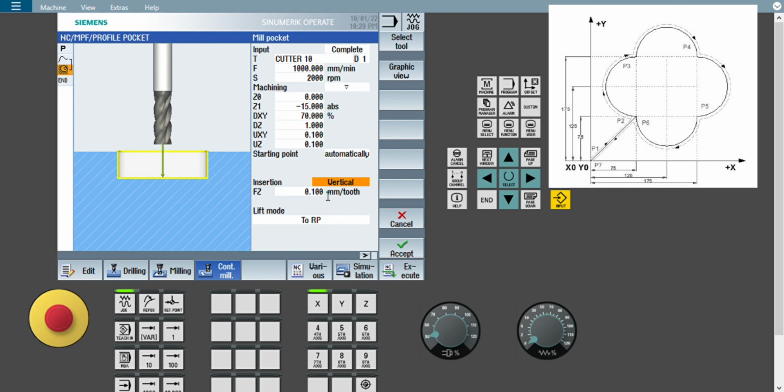So this is the vertical option, and if you press this vertical option, you need to give an insertion feed, that is, 100, 1000, whatever you want to give. Always give 100, 200, that is more than sufficient if you are not pre-drilling a hole. And if you are pre-drilling a hole, then you can give more feed also, like 1000, 2000, whatever you want. Second option is the helical option. This is the safest option, and aerospace and defense industries popularly use this type of option. So this is the helical option, and you need to give the EP and ER.